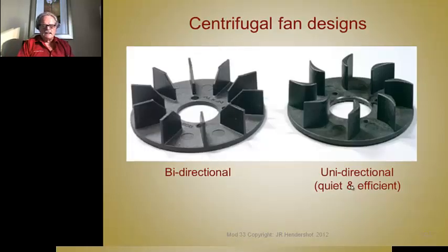There's a wide variety of fans that are used that are either mounted inside the motor, in between the bearings, right on the shaft to circulate air inside of there, or suck air. These are centrifugal fans to suck air through an end bell and out past the end turns of the conductors on the rotor, and blow finally onto the end turns of the stator.